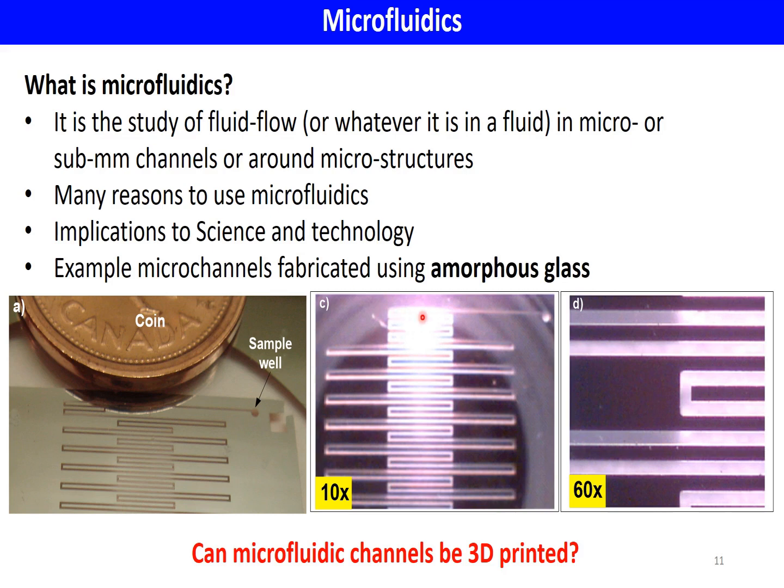This was done for polymerase chain reaction amplification applications, and it's only when this gets enlarged 60 times that we can see a very nice channel around here and very nice, very well-defined corners. The question is, can such microfluidic channels be 3D printed?